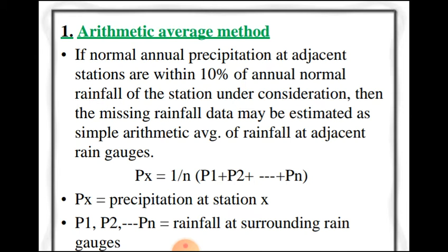The drawback of this method is very simple. We don't give any weight to the location of the gauges in that area. So if we have an area where, let's say, 4 gauges are there, or 1 gauge is there, the method doesn't consider how much area each gauge represents. It's not accounted for in the arithmetic mean method.